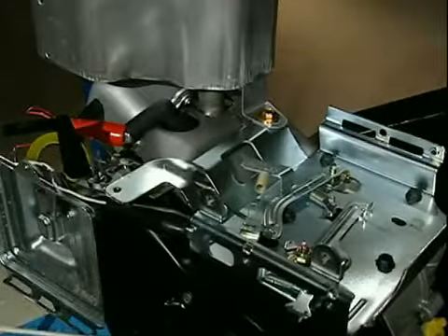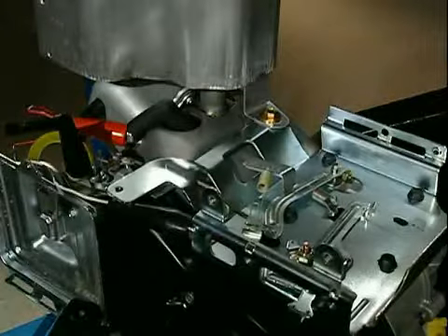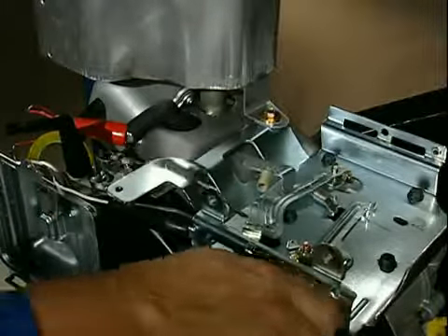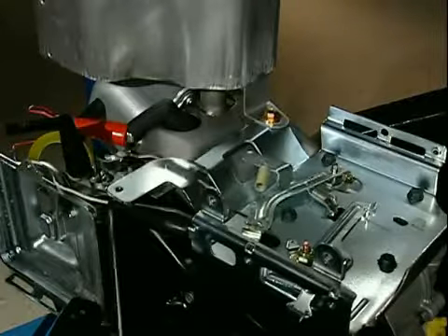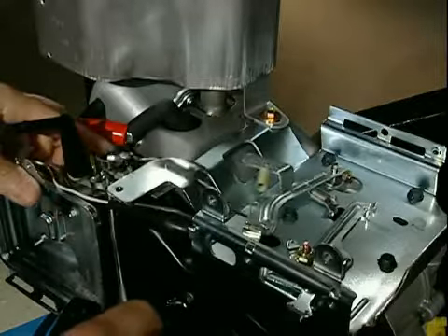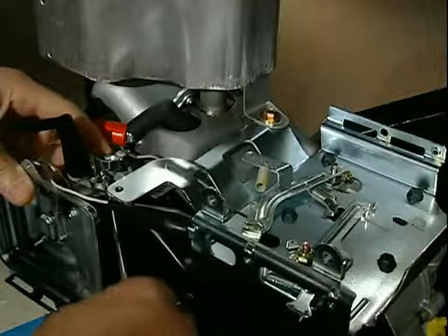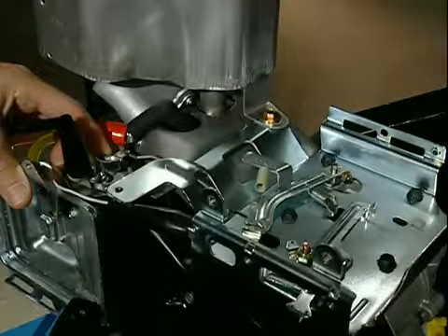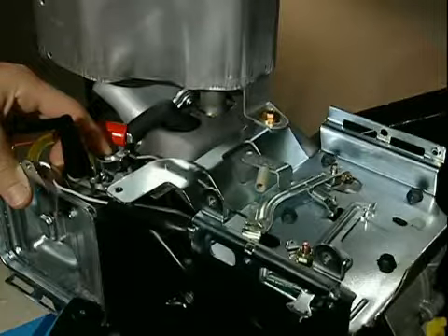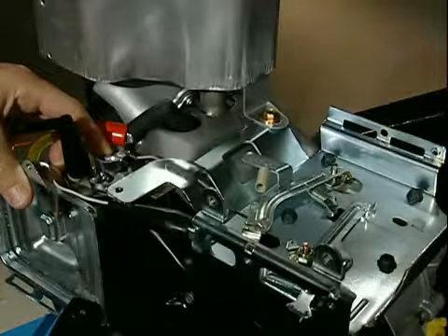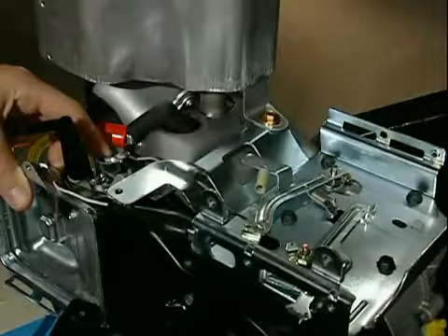Start the engine and bring to normal operating temperature. Position the throttle control at roughly half throttle. Screw in the idle stop screw until engine speed is in the 2800 to 3400 RPM range. Manually hold the throttle shaft against the idle stop screw. If hunting and surging go away, the problem is in the governor system. If they continue or the engine stalls, the problem is in the fuel system. Repair fuel system and recheck.